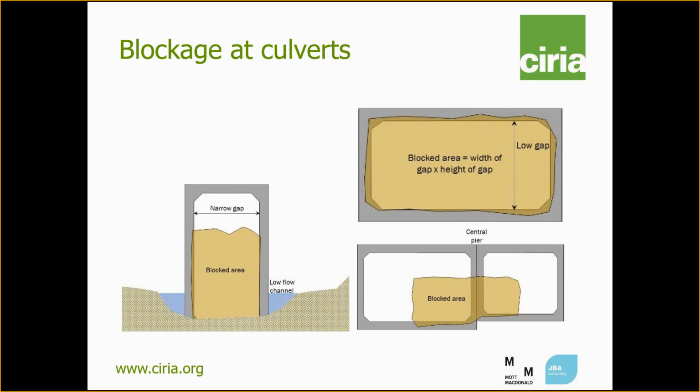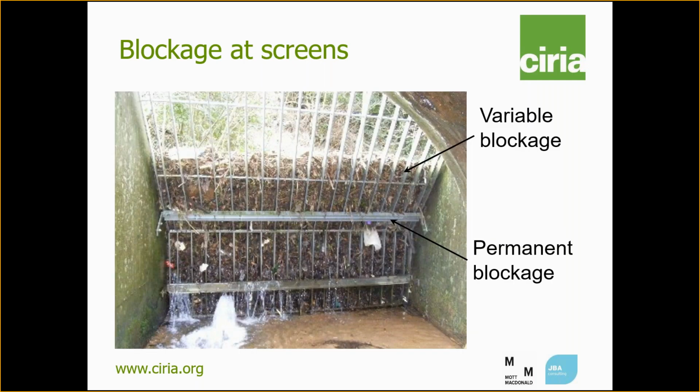And data from historical flood events has shown that long debris can bridge an opening if the span or the diagonal is less than 6 metres, or alternatively, if it's less than the design log length, that is the lesser of the upstream channel width and the maximum length of a sturdy log that can bridge the gap without breaking. Screens are unlikely to remain clean during flood conditions, and man-made debris, vegetation and sediment can accumulate between maintenance.